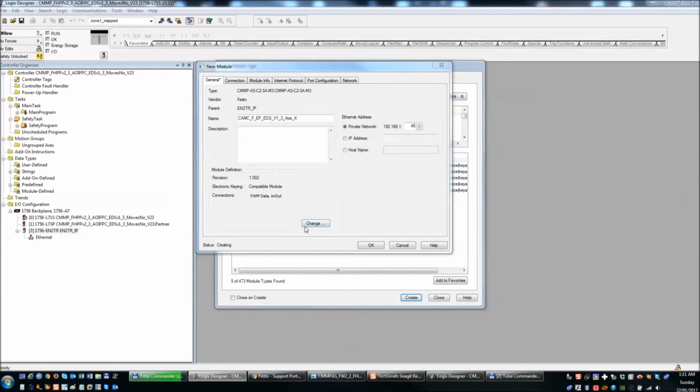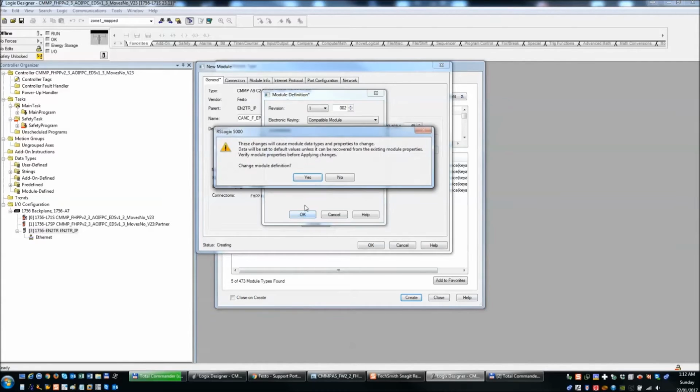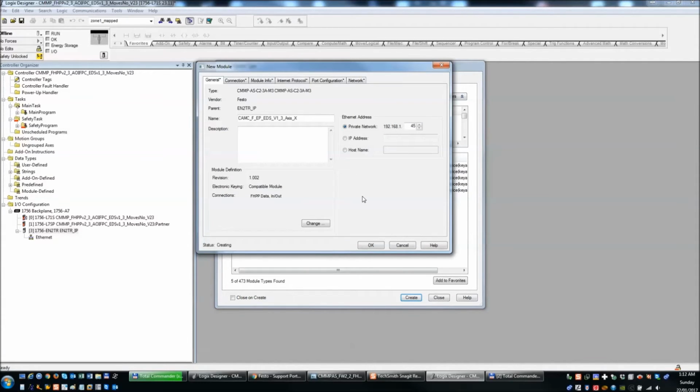And we're going to do 16 and 16. And we're going to do SINT. Okay. Yes. We're doing 16 bytes, and I'll show you later why. Okay, because it's configurable. The controller itself is a configurable thing with relation to the size of bytes. Basically, the basic configuration has 8 bytes, and then you move into another 8 bytes after that for another standard area of data, and then beyond that, it's configurable as well, but specific to the project itself.